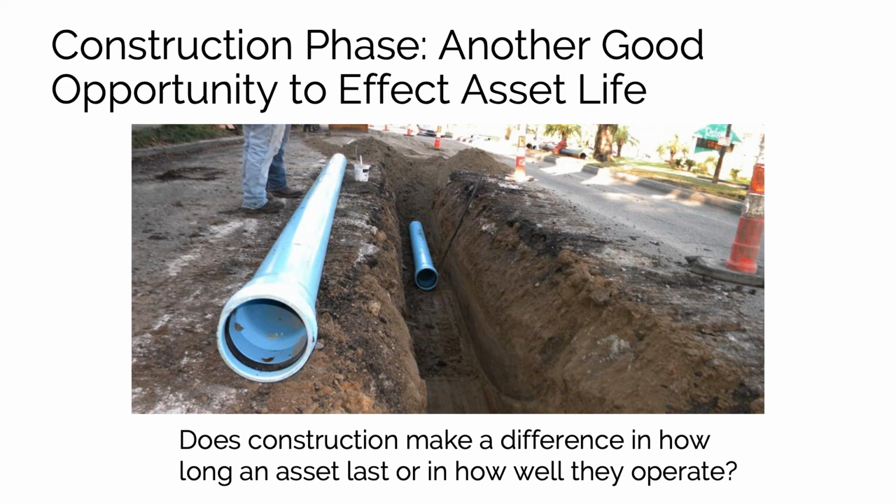I'm sure that any of you out there listening who are involved in, say, pipe assets, if you've ever seen pipe that was poorly installed, you'll have a lot more problems with that kind of pipe. For example, there's one utility that we worked with that had inadequate bedding sand, and they were having a lot of plastic pipe failures because there's a lot of hard rock underneath the pipes, and it was causing cracks and breaks in the plastic pipe. So instead of lasting, say, 75 or 100 years, the pipe was lasting less than 10.